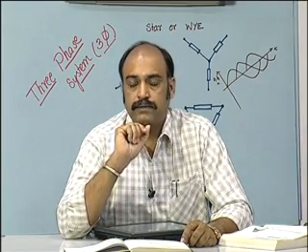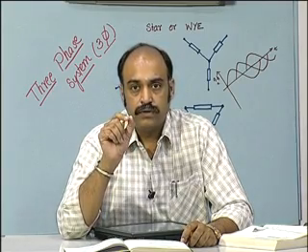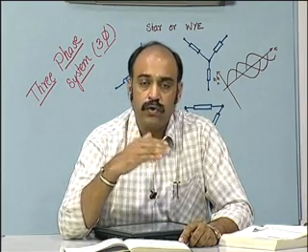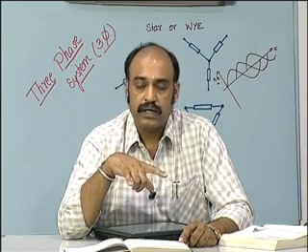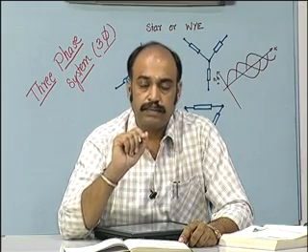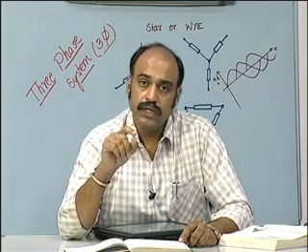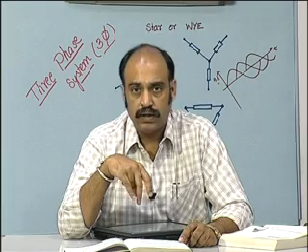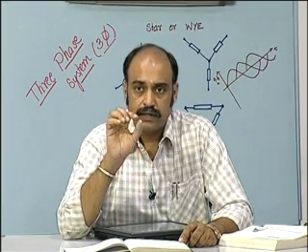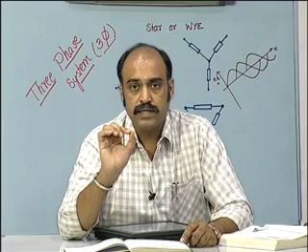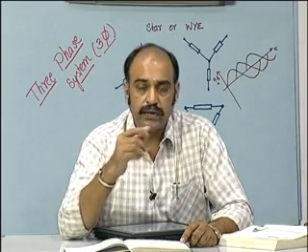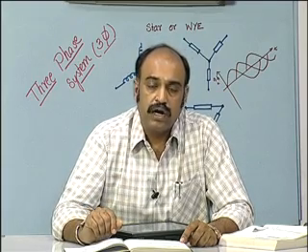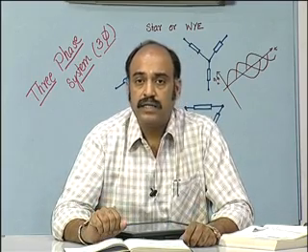in a way such that if an effective value of current I is flowing through the reactive phases, that is the capacitance and the inductance, root 3 times I will be flowing through the resistive phase, that is the actual resistance. Or in other words, if some load current is flowing through the load resistance, that current divided by root 3 should flow through the reactive components that we put in the other two phases.